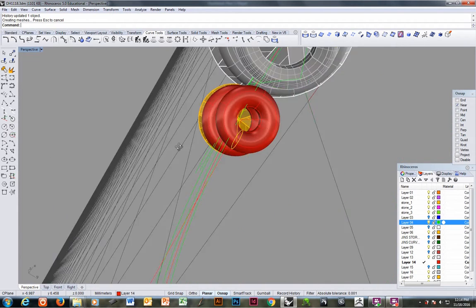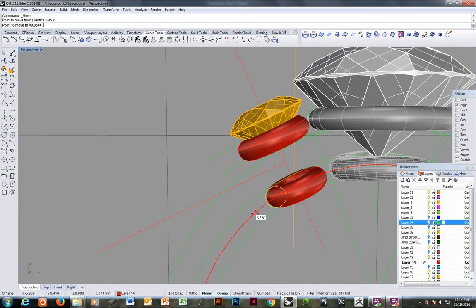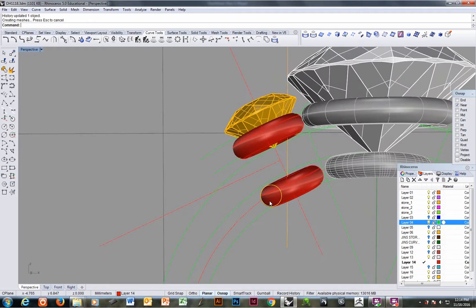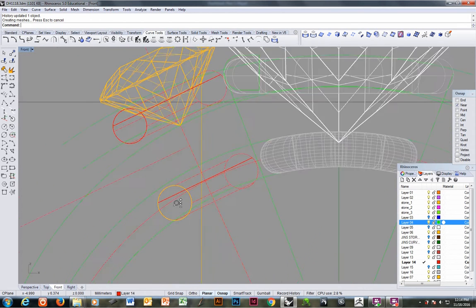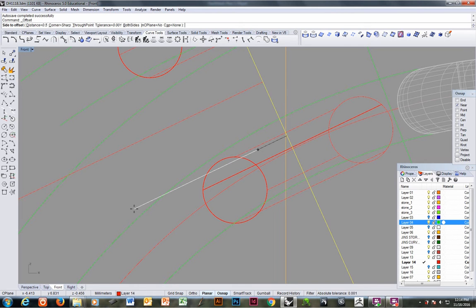I don't want this to close up on the bottom, and it's already kind of closing up on the bottom. This is going to be a fairly straight little setting. It's alright. And I want this to move up to where it's exactly centered in this. That's not going to be easy to do, Jen. Sure it will. Curve, offset this curve, through point, center snap.